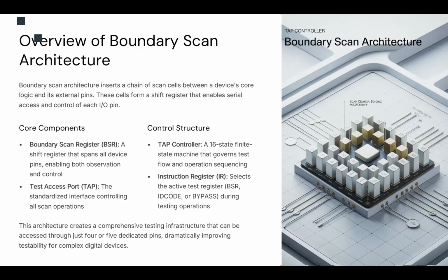For example, if two of the pins are short-circuited with each other, and we inject several types of test vectors, we will see that in all configurations these two pins always have the same values, no matter what the test vector is. That means those two pins are short-circuited. Or if one of the pins is short-circuited to ground, no matter what test vector we inject in the TDI, what we read at TDO is that that pin is always zero. That means that pin is short-circuited to ground. This is the debugging test and fault detection that we are talking about.